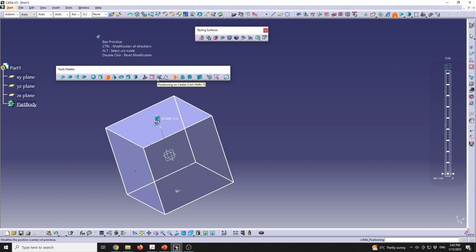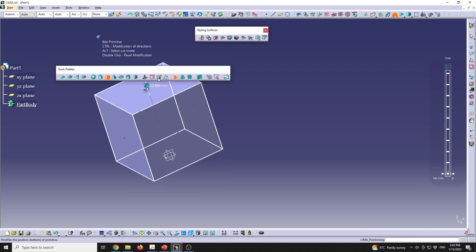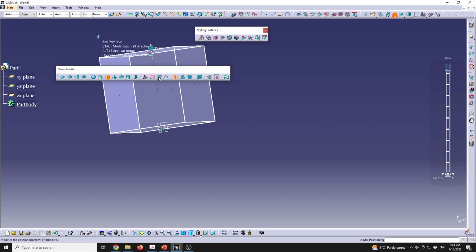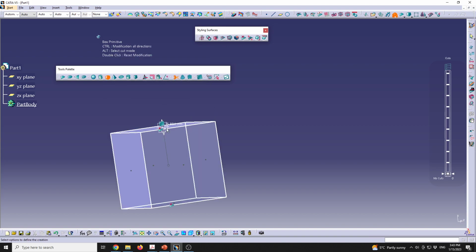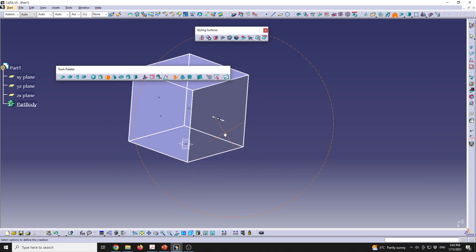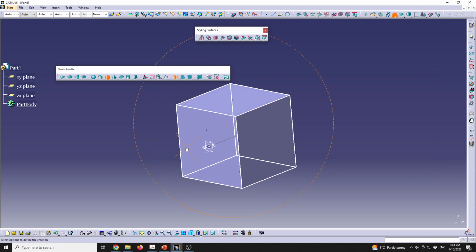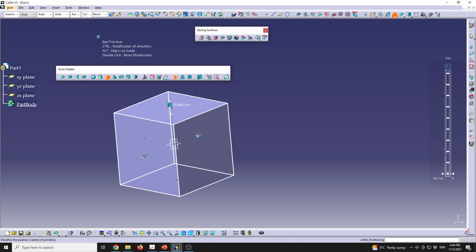After that, the following button will be regarding the positioning of the element. So we have positioning in center, and as you can see, my cube is positioned within the axis reference. But if I go like this, with one click it will be positioned on the bottom of my reference, and with another click it will swap to the other side, so it will be on the top. So currently this should be my view orientation. We're gonna see it at the bottom, so you're gonna have the z-axis going at the top. Again, I can have that swapped for the positioning to go back to the center.